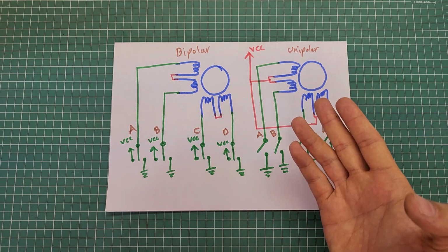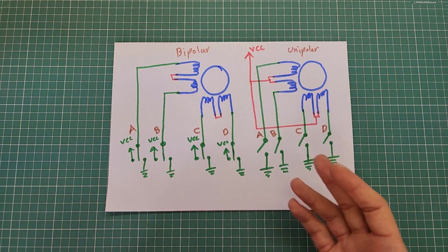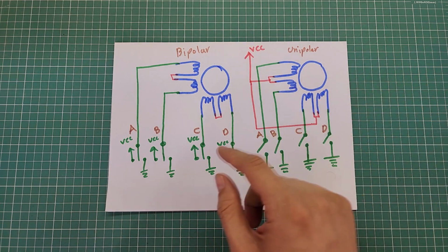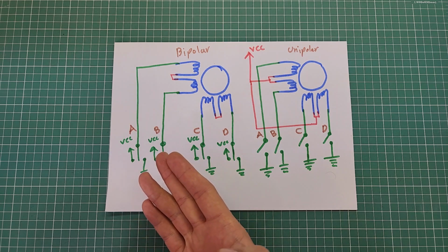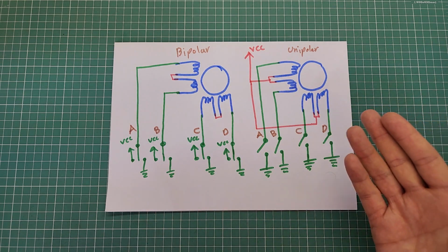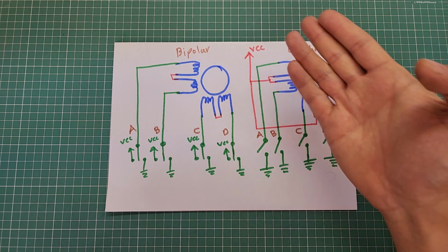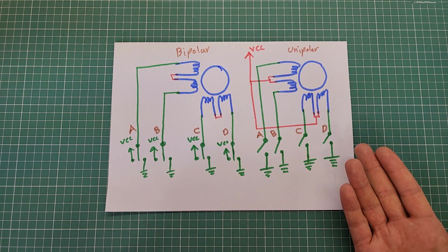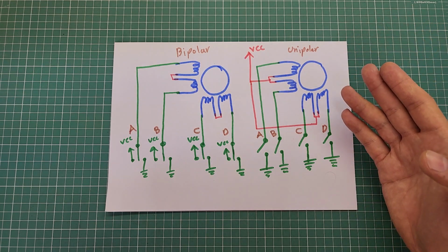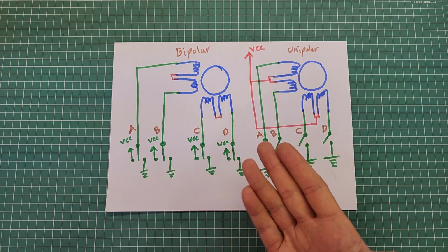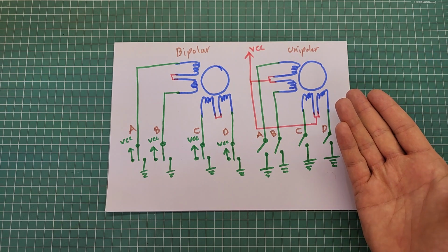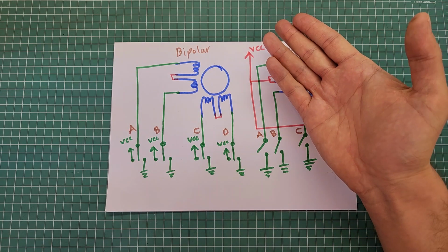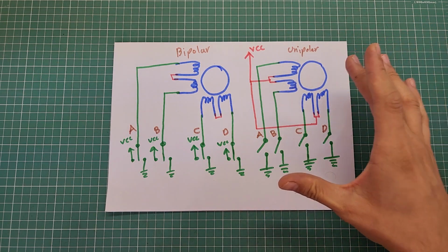If the direction of current in all windings inside the stepper motor does not change at all, we call the driving method unipolar, and if the direction of current changes, we call it bipolar. In this structure, we have connected common wires to source voltage, so you can drive the motor by sinking each of A, B, C or D wires, and it is obvious that the current will always flow from common wires to A, B, C and D wires. In this structure, it is not possible for current to flow from A, B, C or D wires to common wires, so this driver is a unipolar driver.